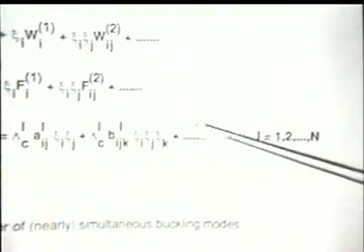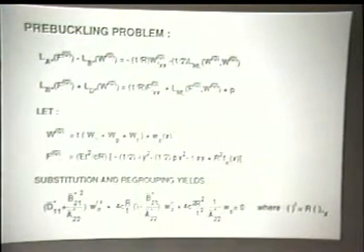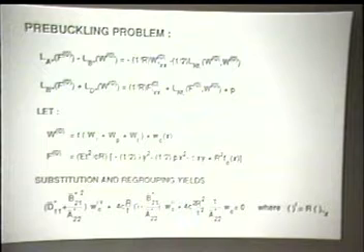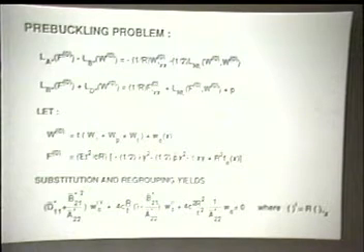You might think there is a summation, but there is no summation over uppercase indices. Okay, now you know how this thing works. You take your perturbation expansion, you shove it into the governing equations, you group them according to powers of the small parameters. The pre-buckling problem is C to the 0th power. It looks then essentially precisely the same as the equations before.